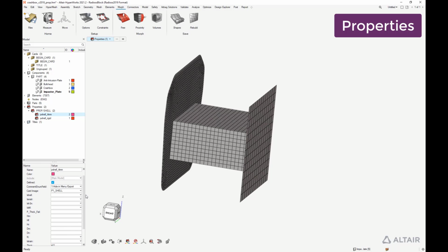This one is deformable, and I need to define a bit more the formulation. First, the number of integration points through thickness. And I'm going to use an under-integrated formulation in the plane, which is standard in crash analysis, but that may lead to hourglass deformation.